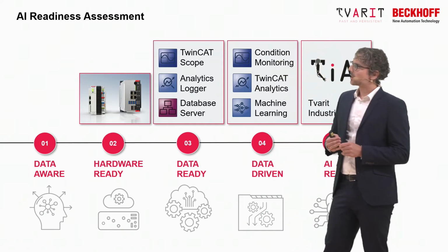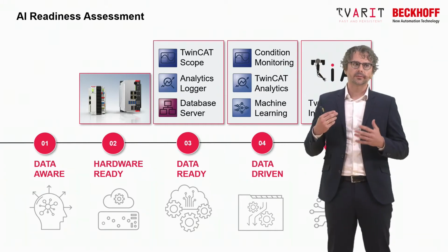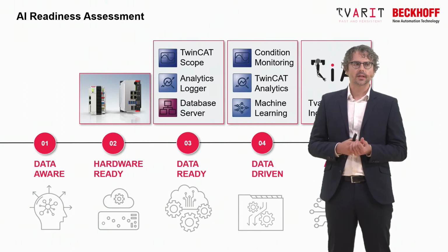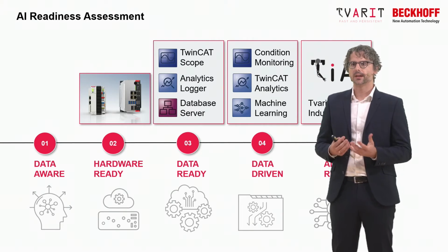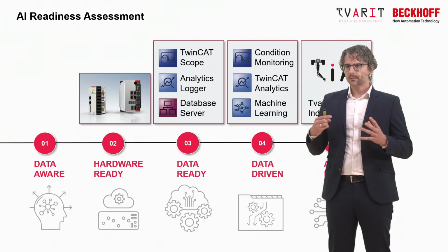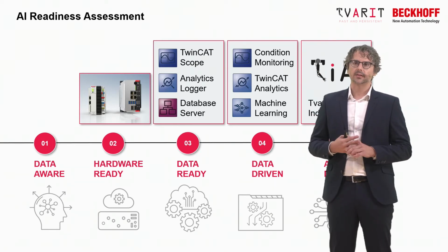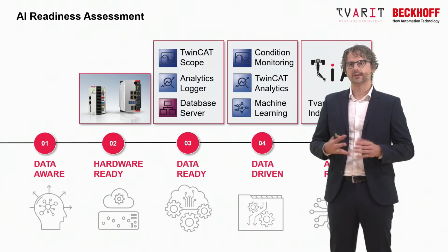Data-driven. So, of course, we also provide you with the tools for first exploring your data. We have the Condition Monitoring Toolbox for doing feature engineering in the PLC, if you like. We provide you tools like TwinCAT Analytics to engineer your signal analysis chains not in the PLC language, but in a graphical interface.